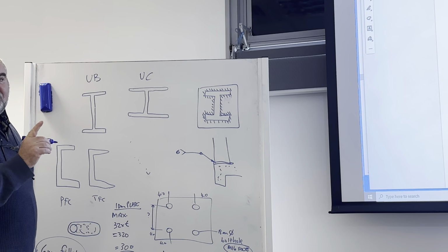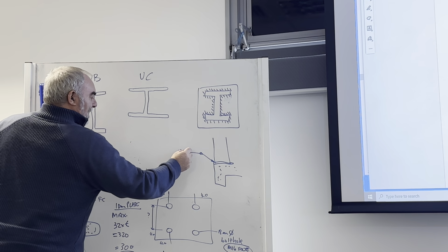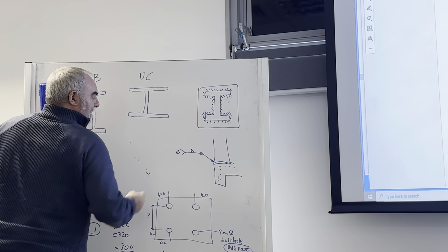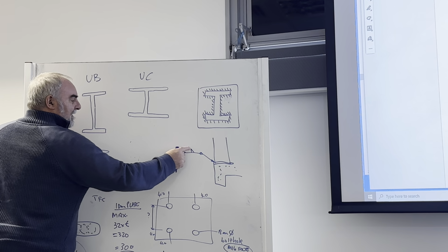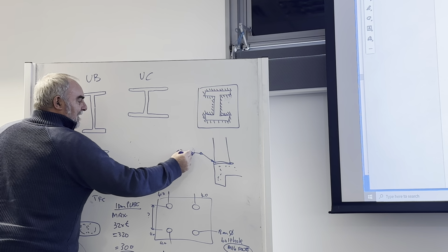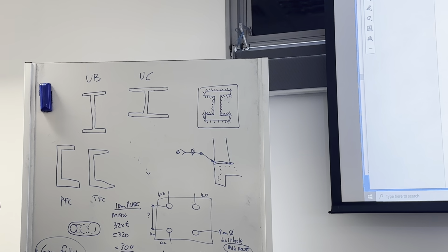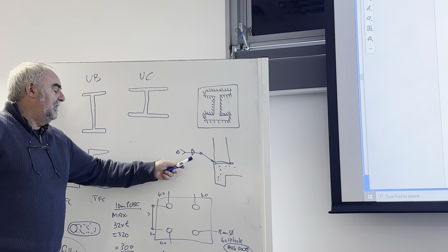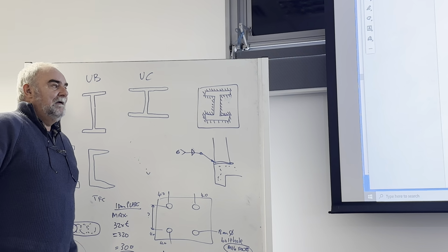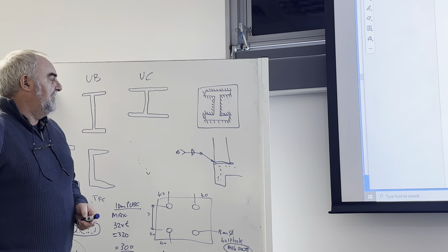Now this is the bit, now this time you've got a choice of 1 and 3. Here's your choices. 1, like a shark's fin. 2, an upside down shark's fin. Or 3, 2 shark's fins. And that's your symbol on site. It's either 2, 1 at the top, or 1 at the bottom. Okay? And that will represent a 6mm fillet weld.